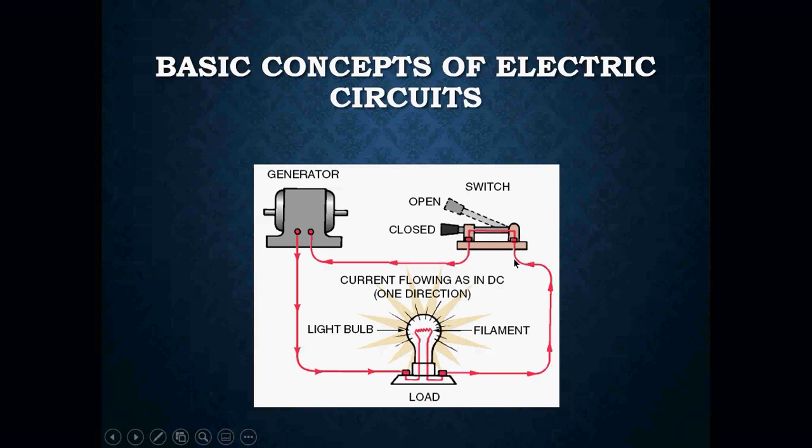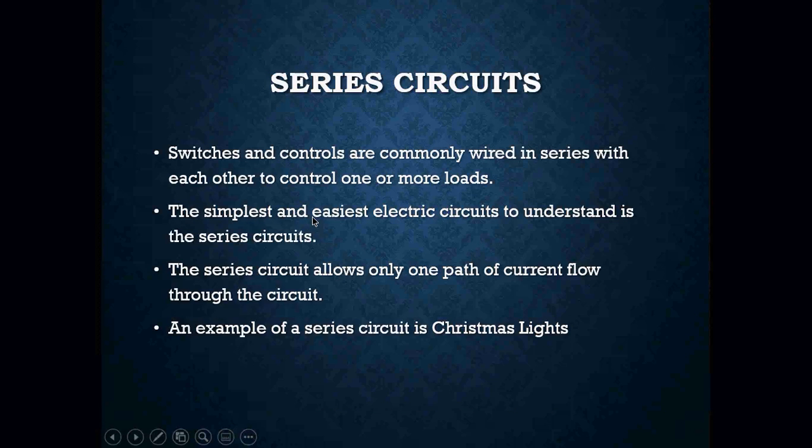Our switch is on the neutral side, which is perfectly fine, because a switch is nothing more than a power passing device. It could be on either side, as long as you're using it to make and break a circuit, you're okay. So here you have an open switch or a closed switch. If I close it, electricity is allowed to pass through that switch and then right back to the power source.